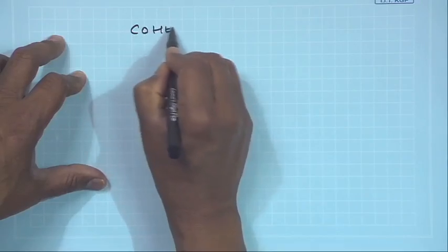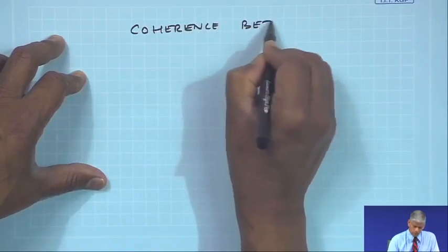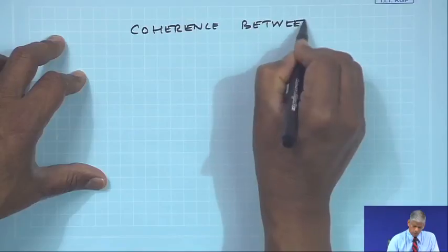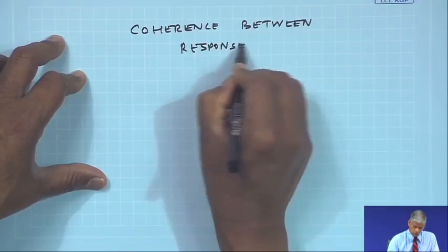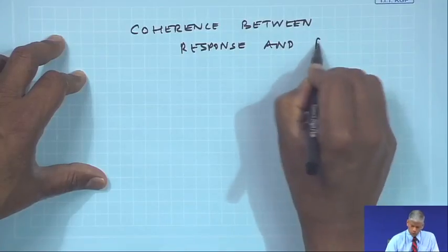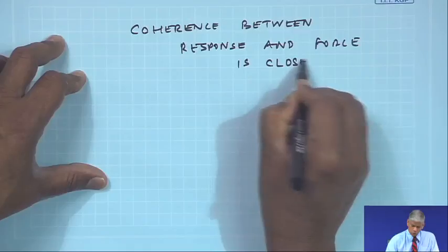Your measurement is good if the coherence between response and force is close to 1.